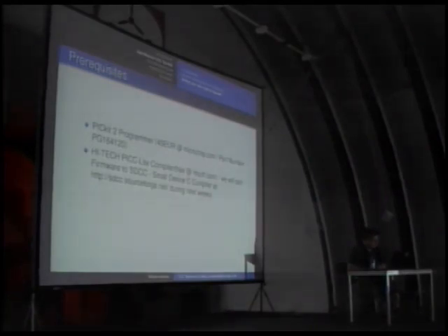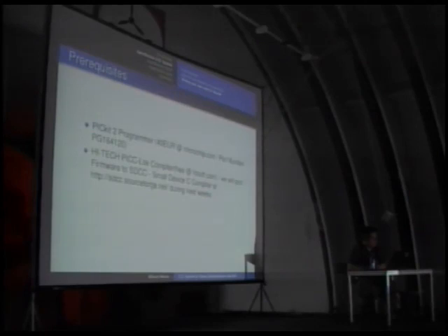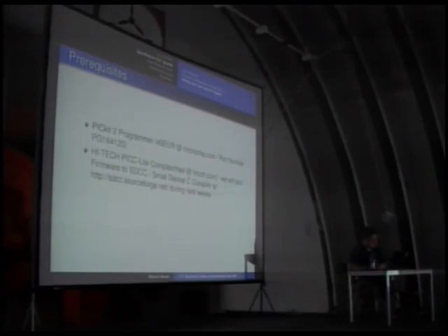We used, for the current software, this high-tech PICC Lite compiler, but it turned out that only few people participated because you had to use the Lite version of the compiler, which only supports half of the flash. So we had to throw out the encryption for the Lite version, so everyone is able to build firmware images.